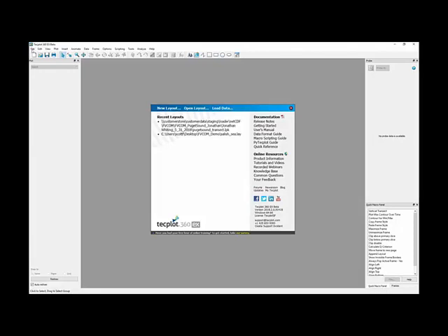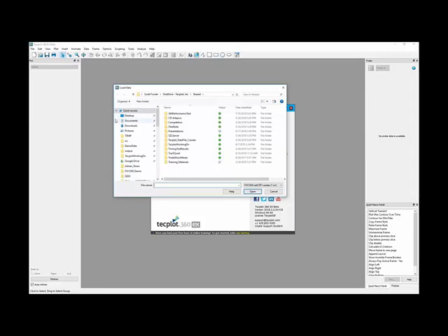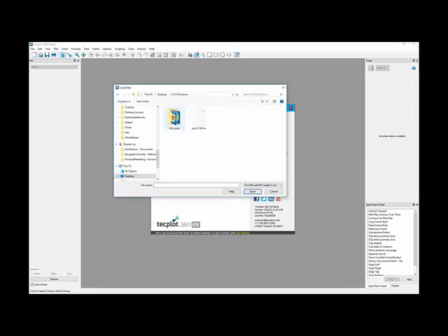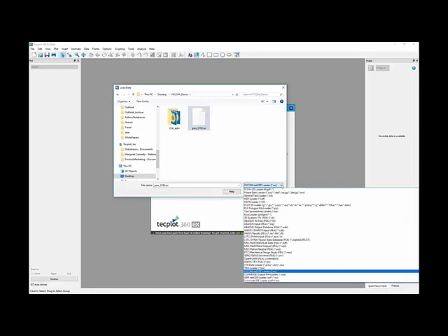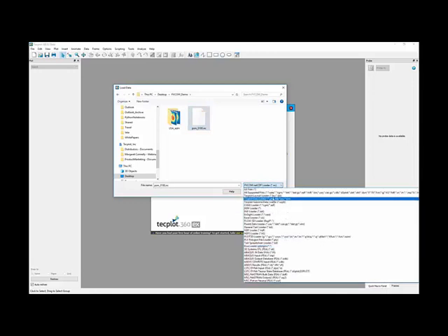All right, so let's go ahead and load our data. So I'll go to the File menu, Load Data, and we'll go to my desktop where I have my FVCOM data set. And I have a netcdf file here. This came from FVCOM. You can see I have FVCOM selected right here. If you do have results from other solvers or other file formats, we have about 35 different formats that we can load here. Like I said, with the Tecplot ADK, you can create your own dataset readers. So if you have a custom format, you can extend this list.